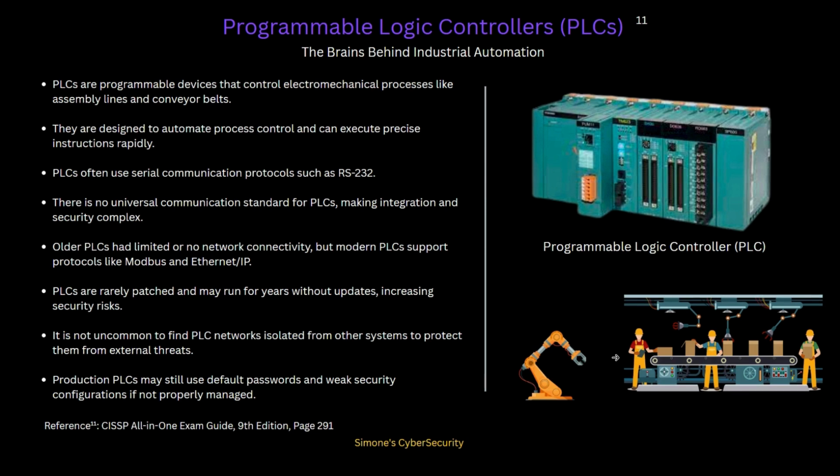Another unique aspect of PLCs that creates security issues is their life cycle. Unlike IT devices, which are upgraded frequently, PLCs are designed to run for years, sometimes even decades, without being replaced. In many environments, it's not unusual to find PLCs that are 10 or even 20 years old and still running some critical processes. That longevity creates security challenges because older PLCs may lack modern security features, they may use default passwords, or they may have no authentication at all, and they rarely receive any patches or updates.